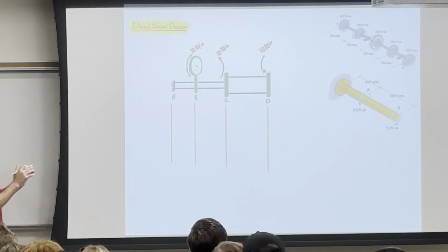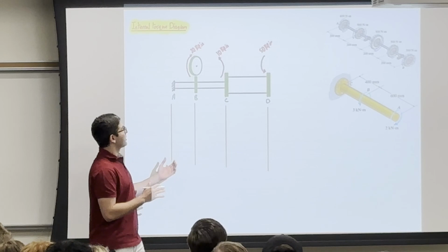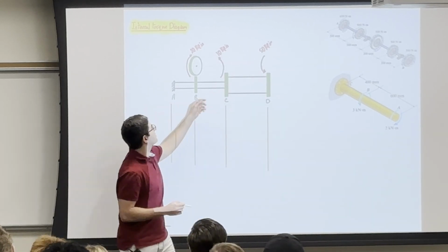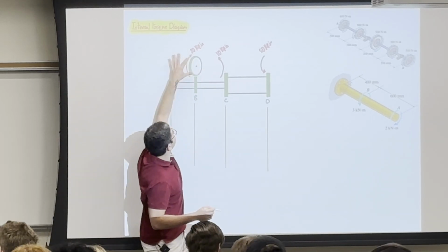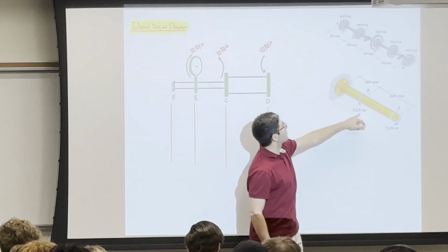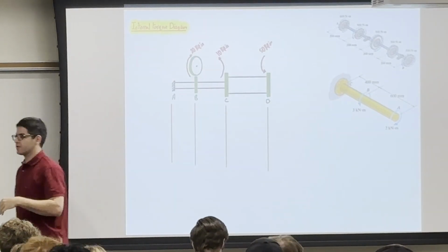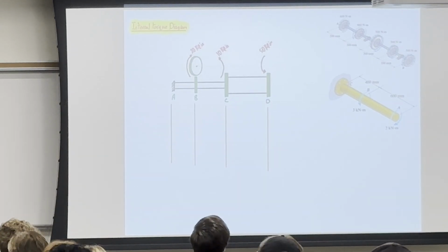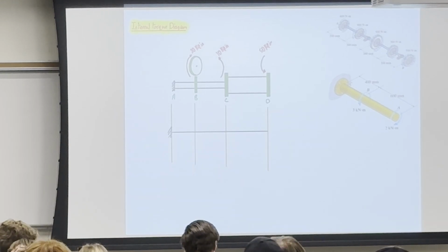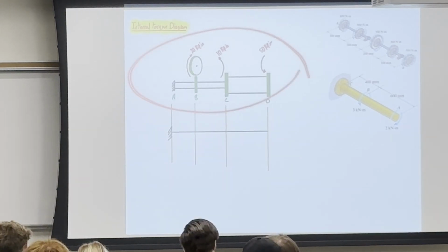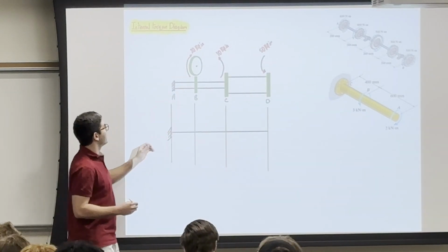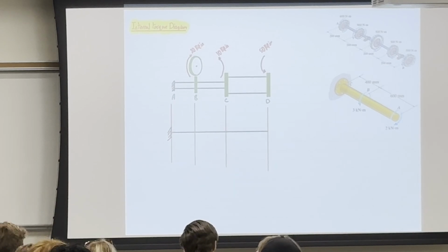It's going to be pretty easy, because when I have a problem like this, you're going to see the torque applied either on these plates, which are gears, or I can just put the torque like this without any gears. And now we're going to use something we call the right hand rule. We can't draw anything with this bending moment, so I want to be able to draw the free body diagram for this beam.